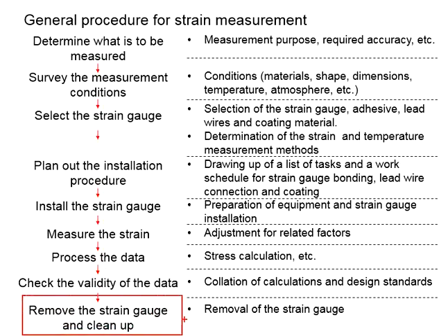Lastly is removing the strain gauge and cleanup. This one depends on the situation. If you are going to continue using the test specimen, then you will need to remove the strain gauge properly. However, if your specimens are tested to failure, or your strain gauge is embedded within the test specimen, probably you don't have to remove the strain gauge, as eventually the specimen will need to be disposed. Make sure you dispose the specimen properly. Abide by the disposal procedures as stipulated by your institution or university.